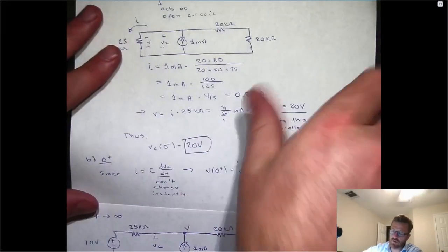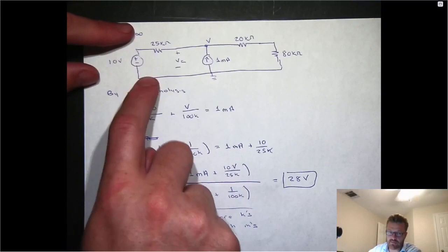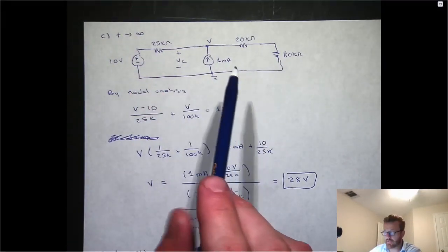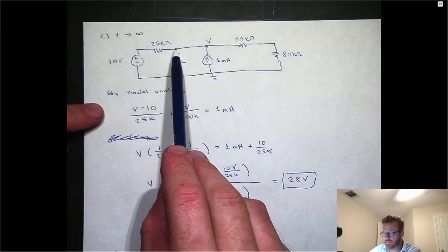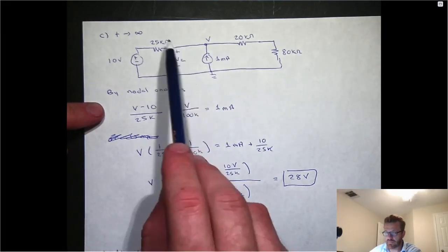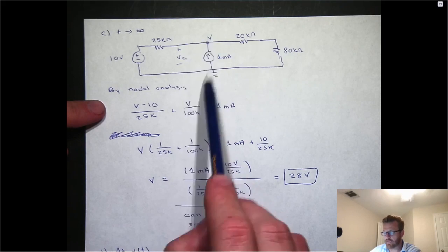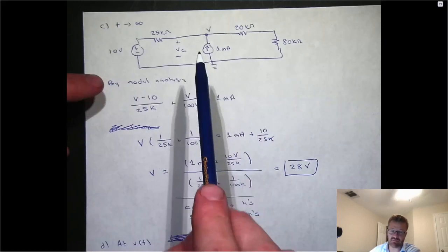So it's a lot like this first circuit, but remember that before t equals 0, the voltage source wasn't on. Now the voltage source is on. So this really is a two-source circuit that you have to solve in some way, and you have to solve for the voltage from here to here. But remember, the voltage from here to here is really just the voltage at that top node, relative to your reference, if you define that as your reference.